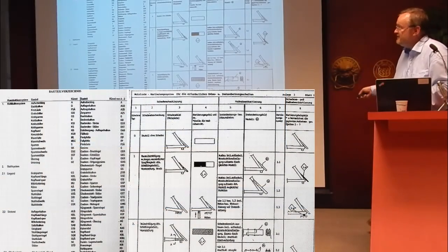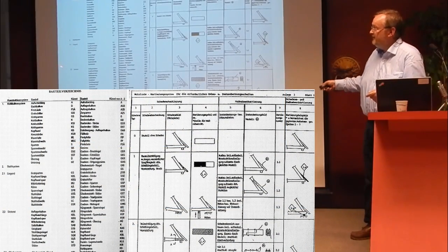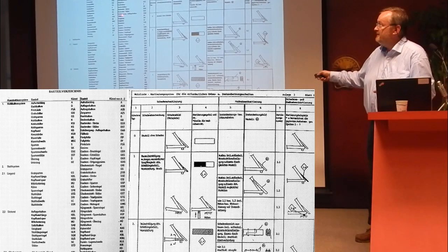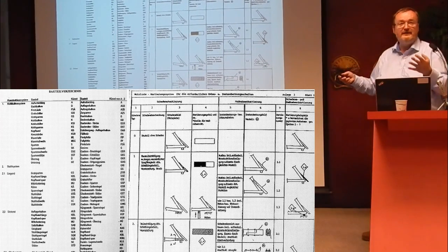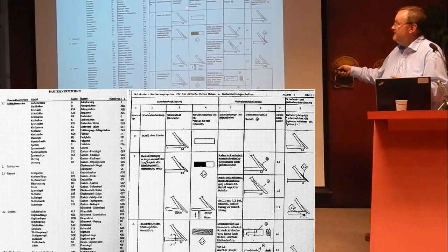In wood construction, we do so. That is our catalog system. So every main part of the roof, of the framework, has a name and has an abbreviation, 1, 2, or 3 characters. And then I found out we have only 9 different damages which are possible at a wooden part of the building. And then I make it in a graphic way and I show, for example, this is rotten.